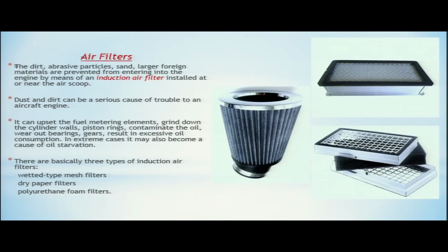So, this filter is filtering out the impurities from the air which is going inside the induction system. This dust and dirt can be a serious cause of trouble to an aircraft engine. In case we provide unfiltered air to the engine, it can have dust and dirt in it, which can be a cause of serious problems to the engine.